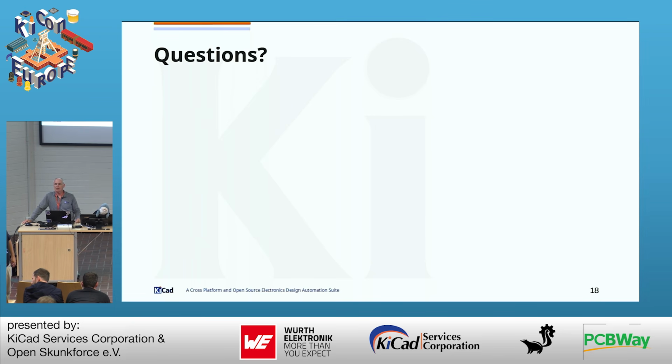When you export the netlist, it's per variant. You were talking about working with the netlist directly. In the variant, you create an export to netlist that's going to send the footprints of that specific variant, and he's going to import the specific variant. But that's actually the information in the symbol, not the net. The netlist doesn't change. The netlist is fixed, no matter what the variant is. What changes is the fields.